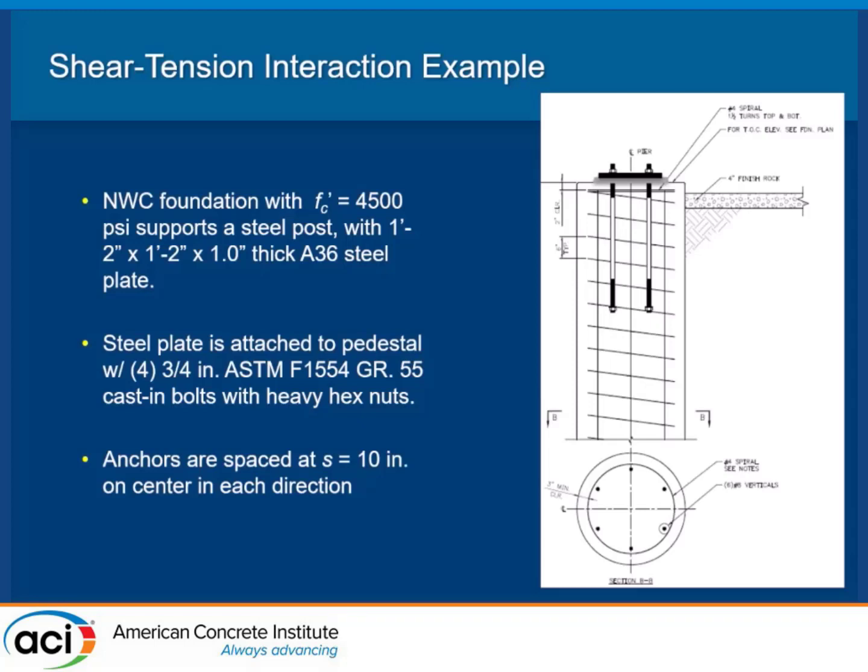And then for shear, the question was already asked, can I use my ties? Absolutely. Depending on how these plates are made, or if this bolt is welded, or you put washers on top and welded washers, you could say that your load is from back here or from here, and I could just put three ties at top or two ties at top, say 3 inches on center or whatever. It's probably enough to get you out of the problem, unless it's just a crazy load. In which case, I didn't have to do any of Chapter 17. I got out of it right there.